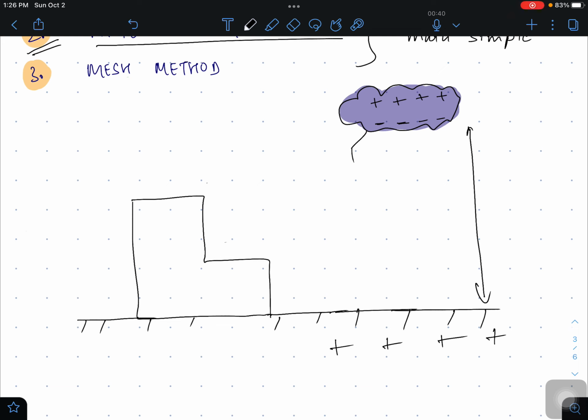So when this comes down, it comes down in a scattered way. They are called the ladders or the leaders. These are the downward leaders, and these are typically of 50 meter length, but it can be of variable length, but just assuming here, and it will carry this negative charge. This will start coming when there is a huge electric field between the cloud and the earth, and air starts to get ionized. In that case there has been a breakdown and this negative charge starts flowing.